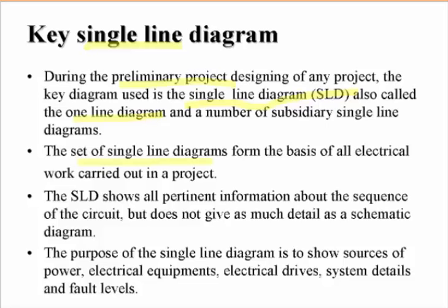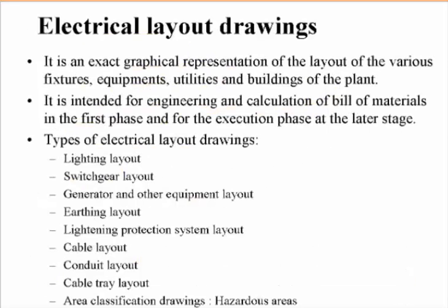This set of single line diagrams forms the basis of all electrical work carried out in the project, and it also shows all the pertinent information about the sequence of the circuit. The purpose of the single line diagram is to show sources of power, electrical equipment, electrical drives, and system details, as well as fault levels. So that's the single line diagram.